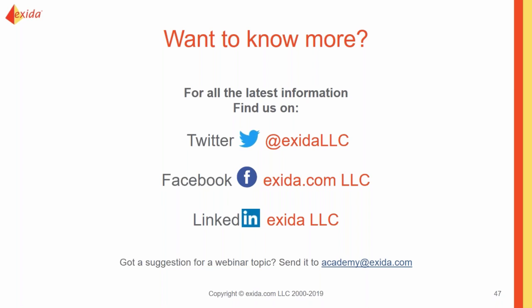The next question is about 2H proven in use data, talking about being limited per the operating device. When we look at the device, we always look at the environment. We have different environmental profiles that we evaluate it at, and the device could be evaluated at multiple different environments and applications. And that's usually in the FMEDA report if there's different failure rates for different operating environments.